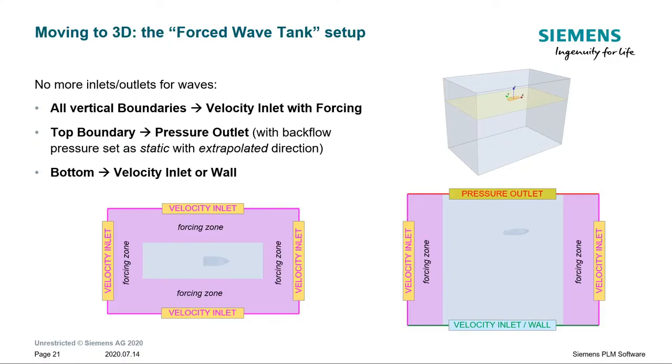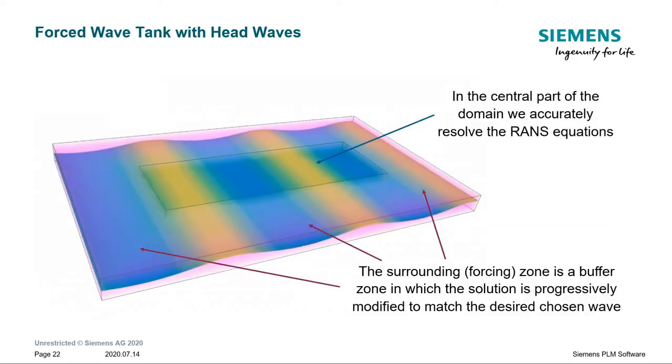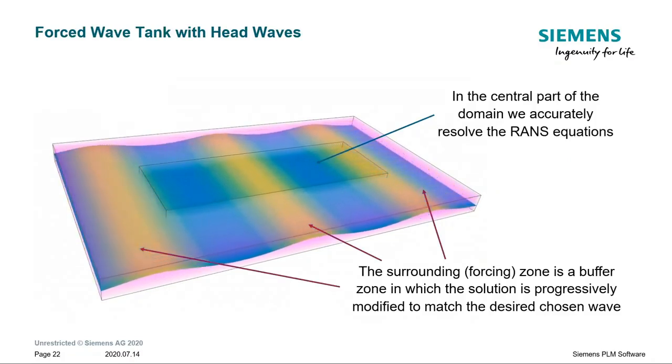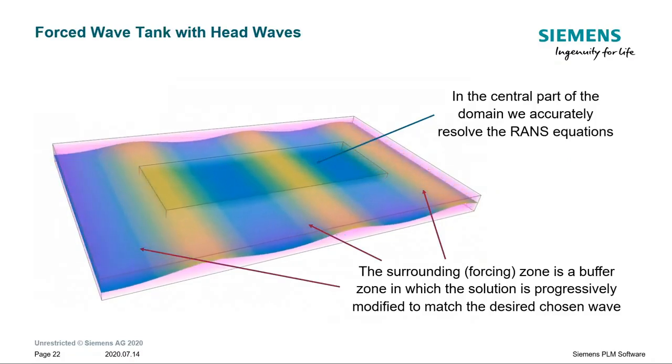At the bottom, on the other hand, it really depends on the type of simulation we are doing, but usually either wall or velocity inlet or even symmetry can work. It's not so important.